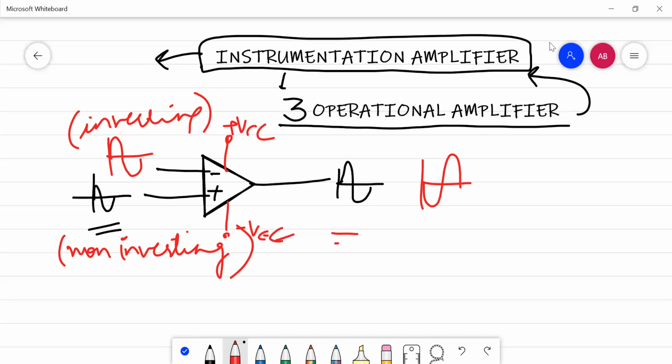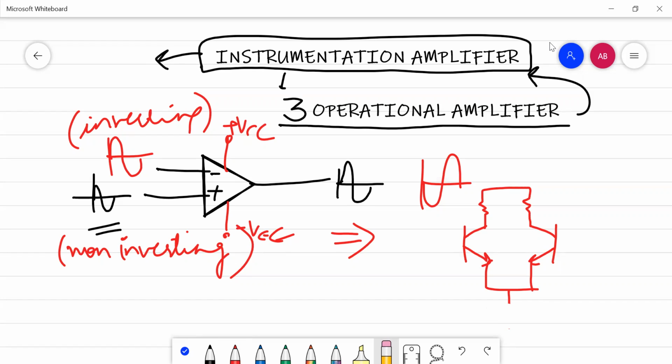So basically what is there inside this operational amplifier? Because all the defects that we are going to talk about, that is, what are the problems in the operational amplifier, come from the difference in the structure of these two transistors, because operational amplifier consists of two transistors that are connected in the differential arrangement. So these both are connected here, not VEE, but we can say here not ground. So here we are going to give it minus VEE with a resistor in between, and here we are going to provide it VCC.